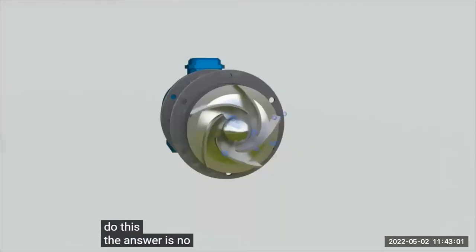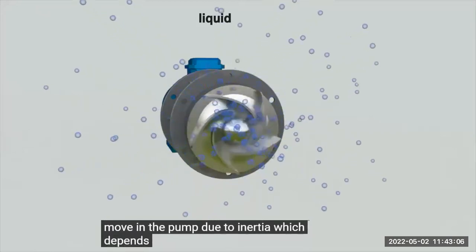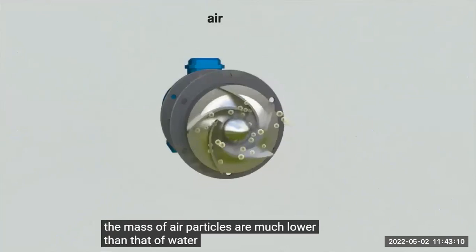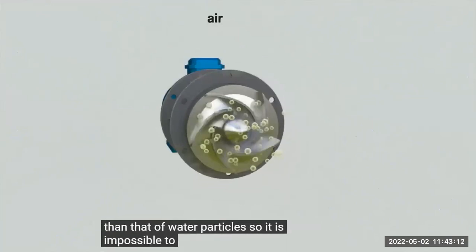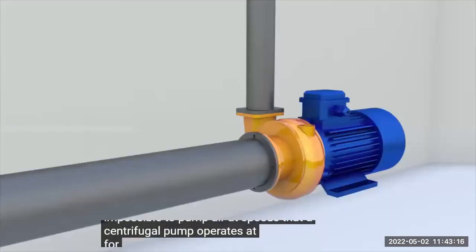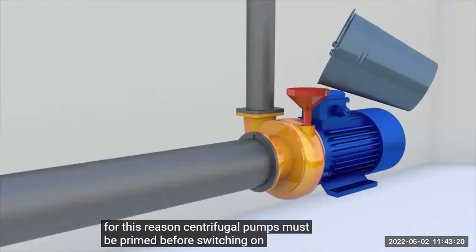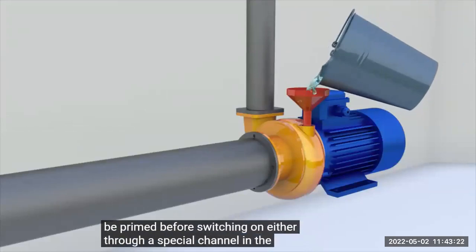The answer is no, because the particles move in the pump due to inertia, which depends on mass. The mass of air particles is much lower than that of water particles, so it is impossible to pump air at speeds that a centrifugal pump operates at. For this reason, centrifugal pumps must be primed before switching on, either through a special channel in the casing or